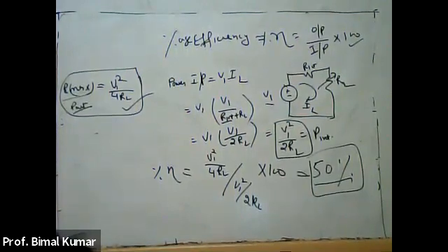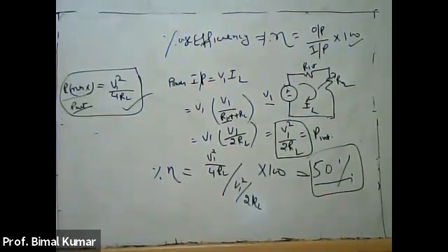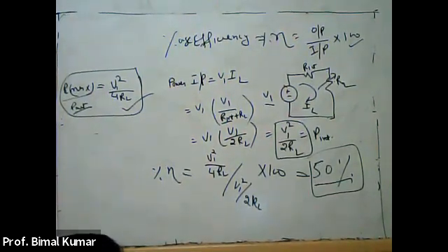That means remove the load resistance RL, then short circuit all the voltage sources, open circuit all the current sources, then apply the simple basics and calculate R equivalent across the load resistance terminal, right?